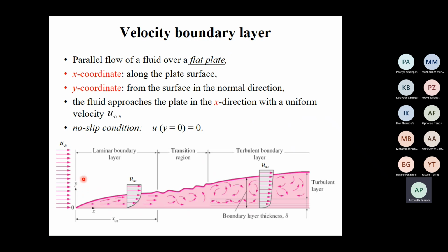No. It's not the distance. No, the distance is x. Okay, so L is on the x-axis. L is depending. We will study it, but if I have to evaluate, for example, the Nusselt number, I have local Nusselt number, that means characteristic length is x, the distance from the beginning of the plate.